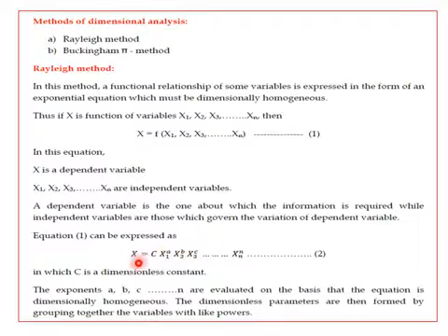So substitute the dimensions of each of the quantities on the left hand side and right hand side, and since it is dimensionally homogeneous, you can work out the powers a, b, c by grouping together the variables with like powers. This will be shown very clearly in the problems: how to find out a, b and c, and then rearranging to form an equation.